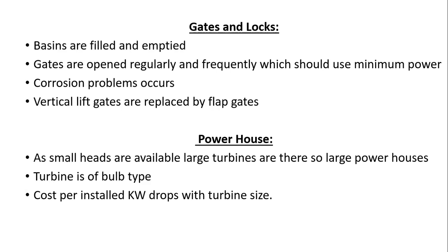Hence, the basin level will rise well above the sea level as the ebb flow area is far less than the flood flow area. We will discuss these ebb flow areas and flood flow areas in further classes. Ebb, as I already said, means flowing back. Ebbing means the flowing back of the tide. This is called ebbing.